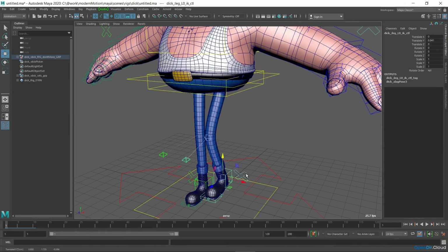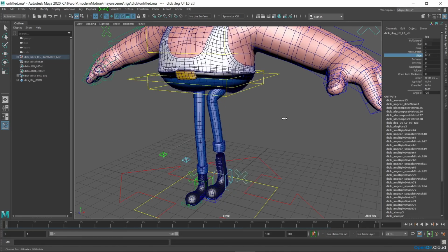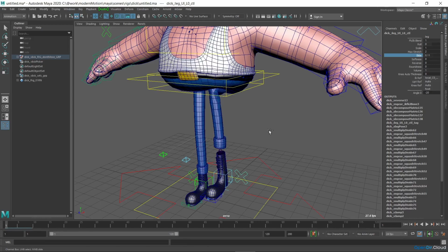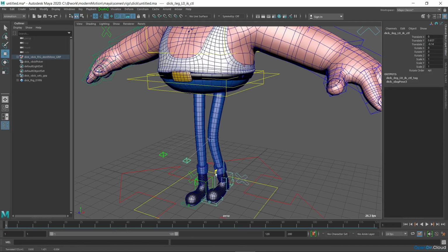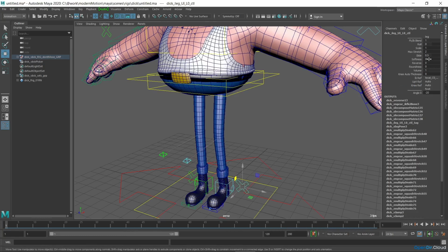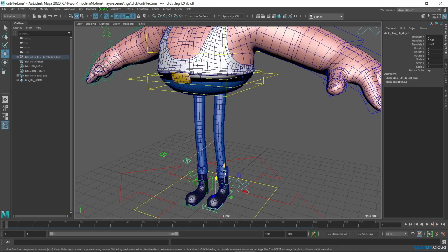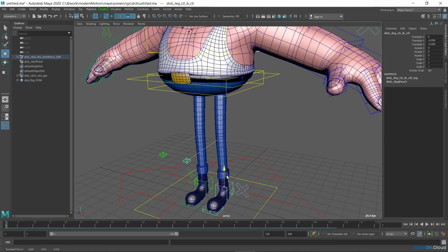The slide attribute shifts the knee to the pelvis joint or to the foot. Softness allows you to smooth the angle at the knee joint when the leg is straight. When the leg is almost straight, small shifts of the leg controller give a very noticeable and abrupt change of knee posture, as if a click. It's rather hard to smooth it out manually. But if you increase the softness a little bit, you can remove the jumps automatically.